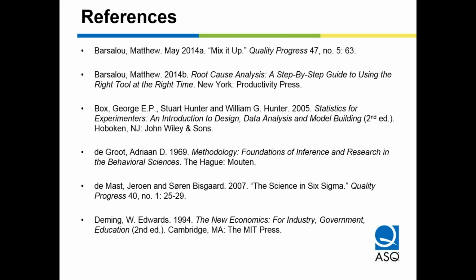From my view, there's 2 types of causes, the proximate cause and the ultimate cause. The proximate cause is the cause closest to the failure. It's what we've observed. It's usually the first one we find. And if things go wrong, it's where the corrective actions are set. The problem is, why did that occur? We want the ultimate cause, the true underlying cause that created a chain of failures.